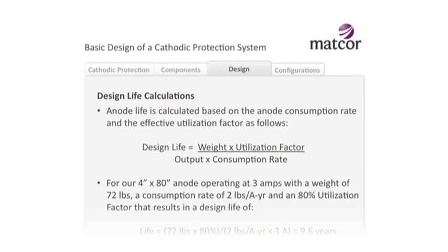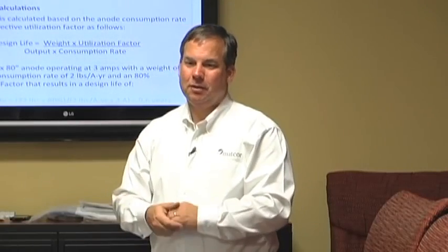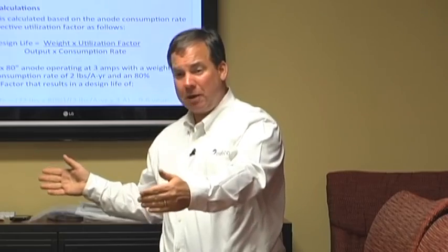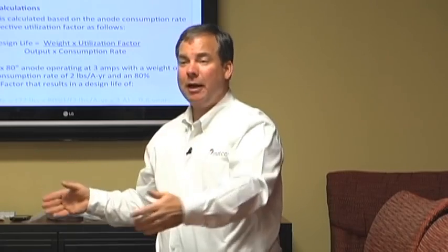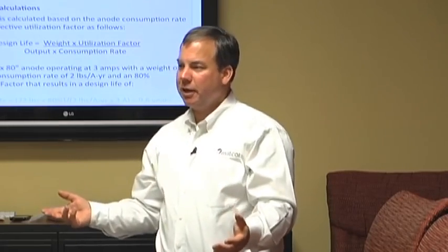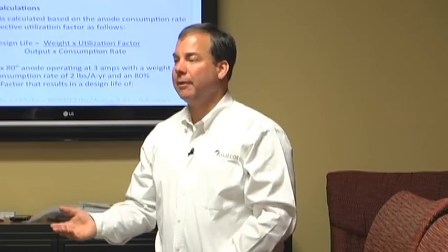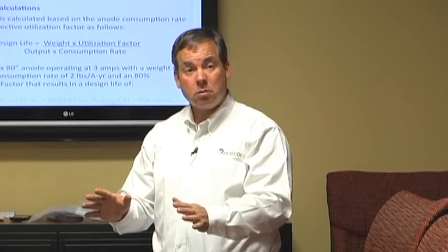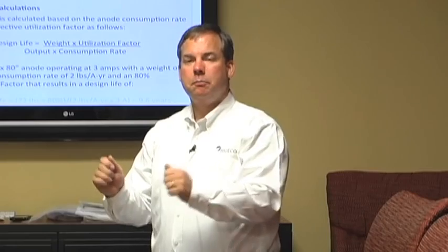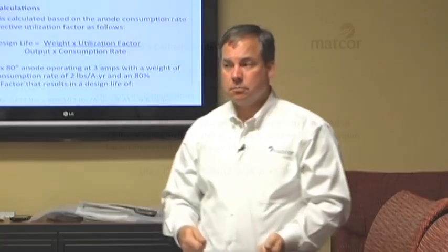Now, often we design it for 10 amps. They go out in the field. They find out that 8 amps is fine. Well, that's great because now it's going to last longer because I'm not running it as fast. Or you go out in the field and you find out, you know what? It wasn't exactly a 100-foot long sheet pile wall. It was 110 foot long, and it's taking a little more current than we thought it was going to take, and we're going to operate that 10 amp system at 12 amps. Well, that's fine. It'll work in most cases, but it might not last as long as you designed it to.